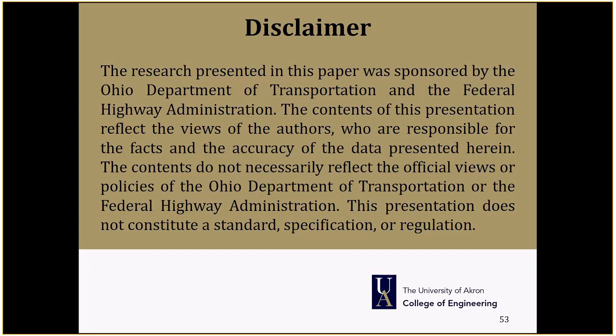One comment, two questions. The comment is, a lot of times contractors don't wait for the tack coat to cure, then they go over it and they rip the membrane out. Question: for the type 2 and type 3 membrane tests, did one work better than the other?